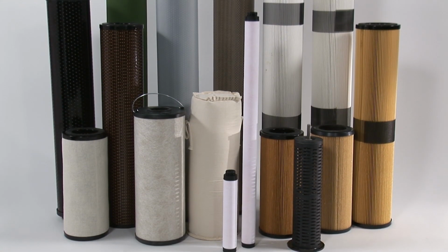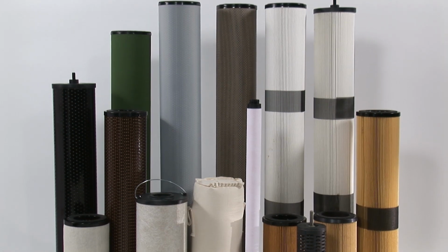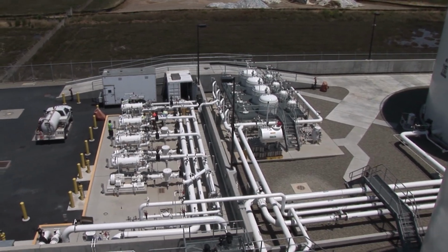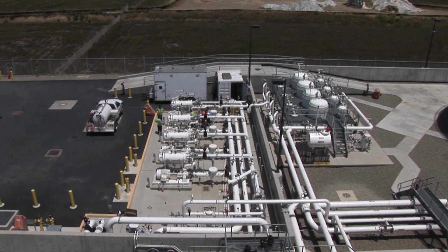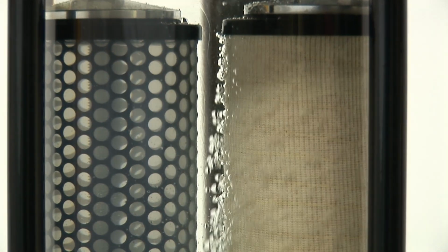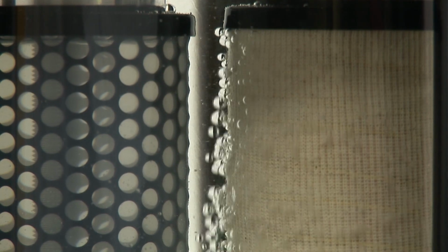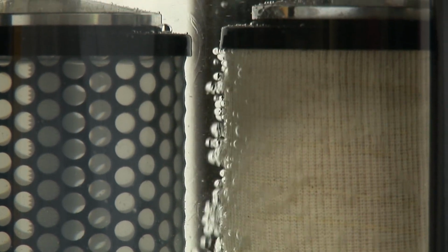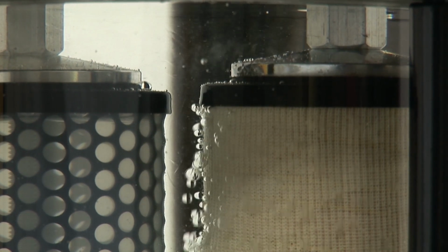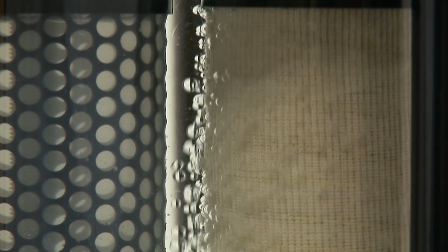Facet has a complete line of coalescers and separators, pre-filters and monitors that meet or exceed Energy Institute guidelines. The backbone of any quality filtration system is the filter separator. It separates undissolved free water from fuel. It also removes solid contaminants. As the fuel and water mixture passes through a coalescer cartridge, the small free water droplets gather or coalesce into larger drops. These larger drops will either fall by gravity into a collection sump or are stripped by the separator cartridges.